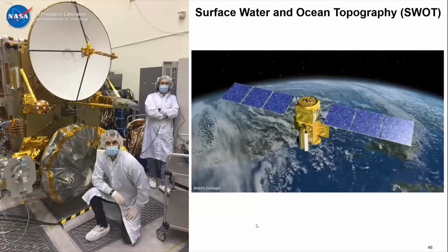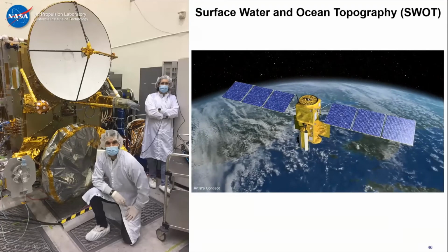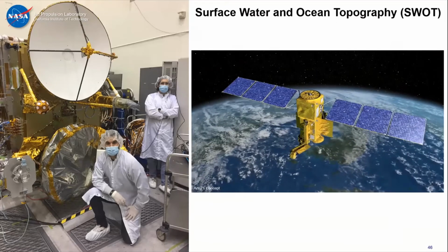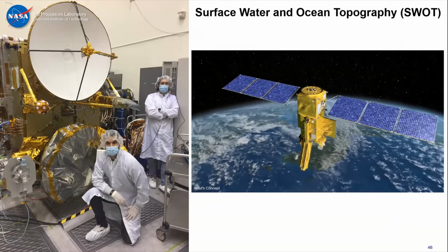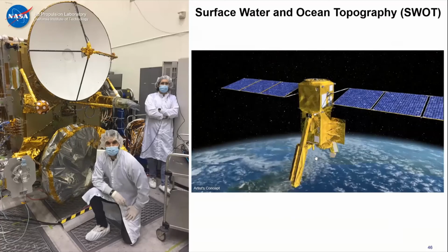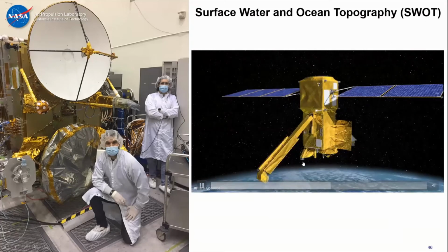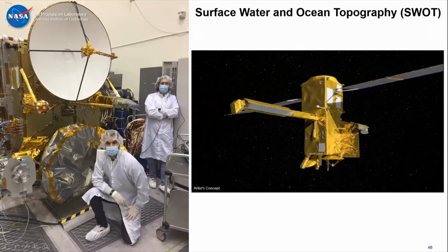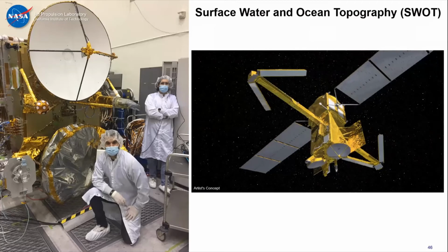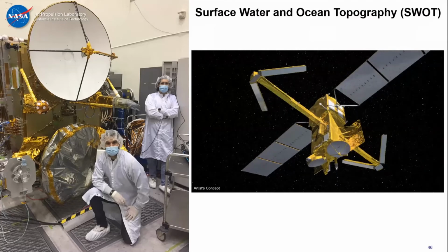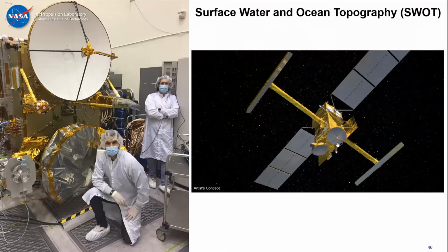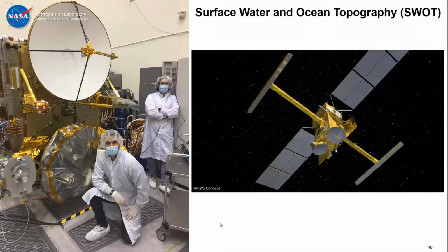So here is a video of the spacecraft deploying the large deployable antenna, which is a reflectarray, and it's very high power. We did a lot of work to make sure that everything will work properly, since we have a very high power being radiated from the radar toward the nadir deck. I'm not going to go into the details for that, but I wanted you to have a grasp of the complexity of the deployment. It's K-band, so the surface deployment needs to be excellent. The deployment accuracy needs to be excellent, and everything needs to be extremely stable because this is an interferometer, so the phase accuracy between these two antennas needs to be very good.